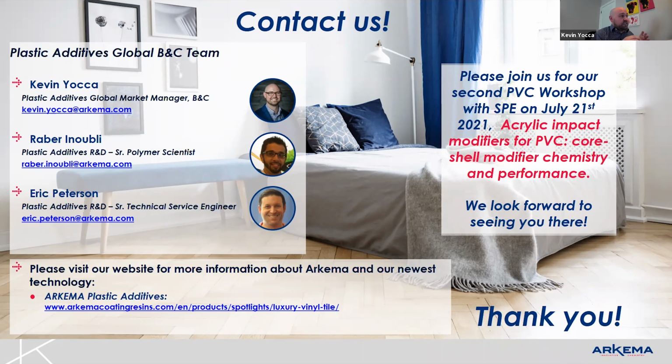You're breaking down the PVC particle, opening up the primary particles, and then trying to engage entanglement to the level you can with the amount of plasticizer. And semi-rigid might be 20 phr; flexible, I was talking to someone just this morning about this, is probably beyond 50 phr plasticizer and then way beyond.